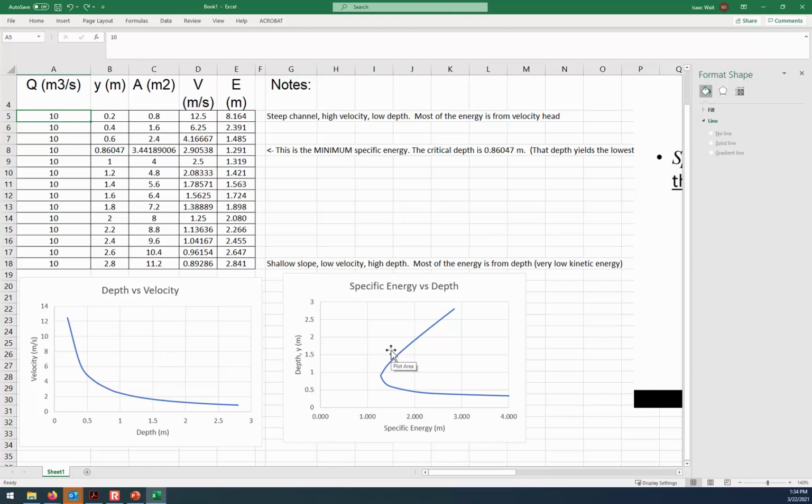If you put an obstruction in, then the way the water behaves is different if it is supercritical flow or subcritical flow. So that's why we're laying a foundation of understanding the flow regime. It's the key to being able to predict how the depth is going to change with things like a change in slope, or if the channel is getting wider. Whether it's supercritical or subcritical is going to be a key factor in understanding whether the depth increases or decreases.